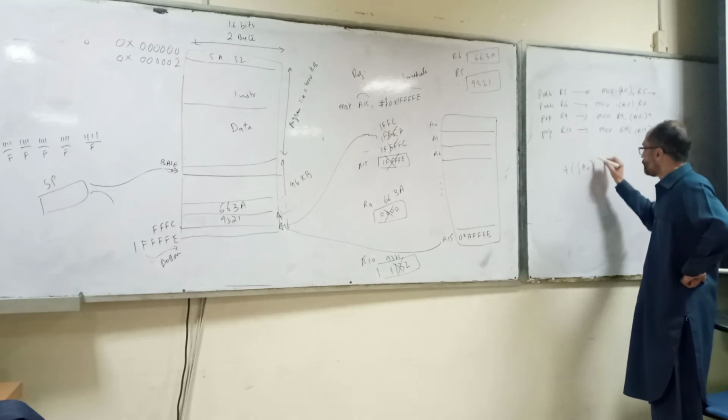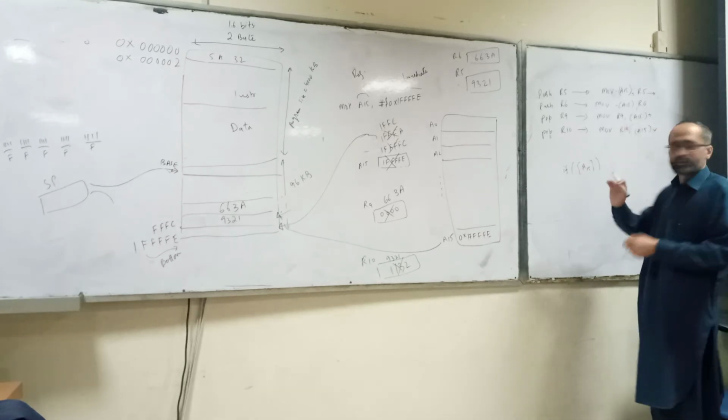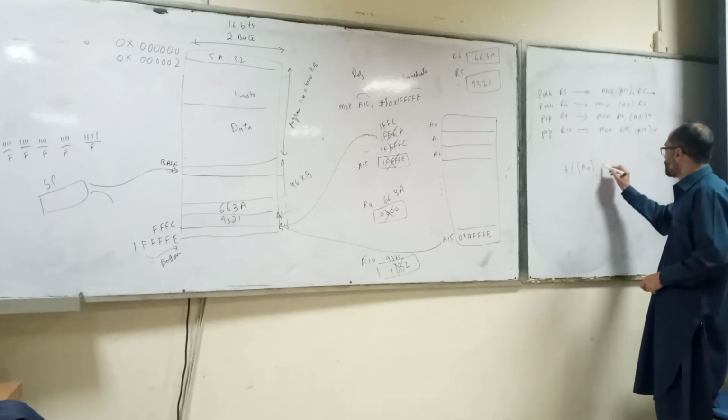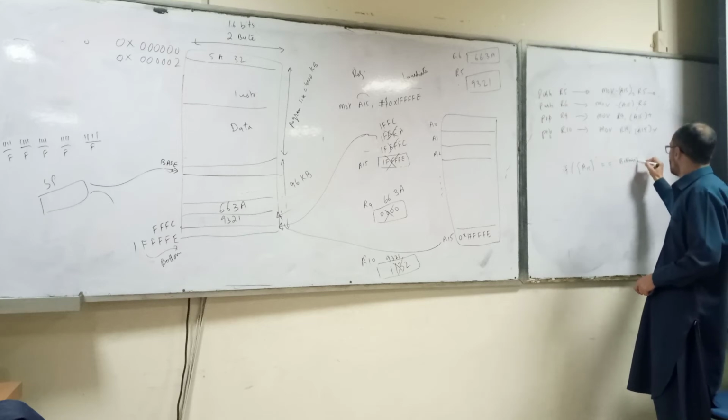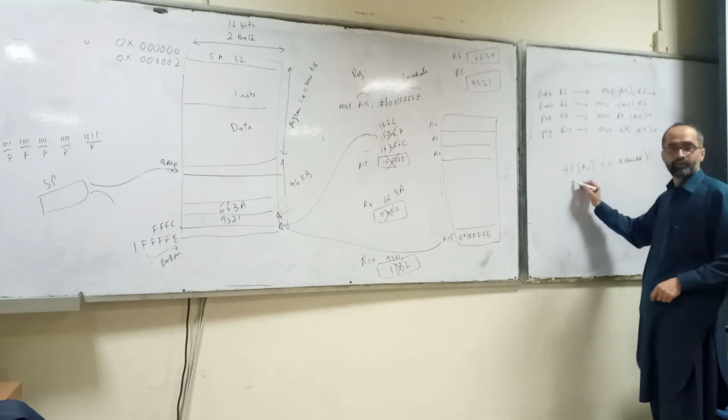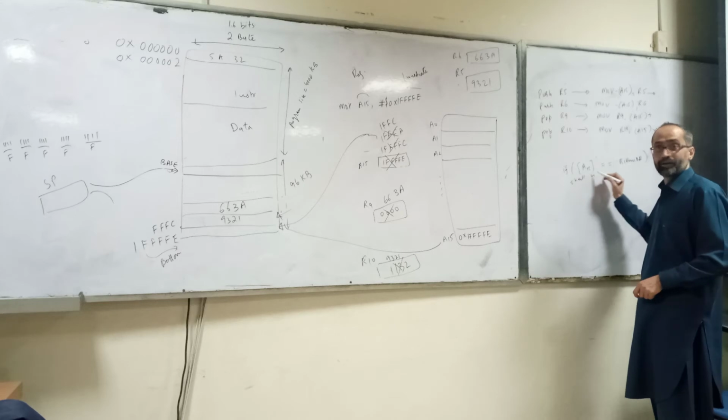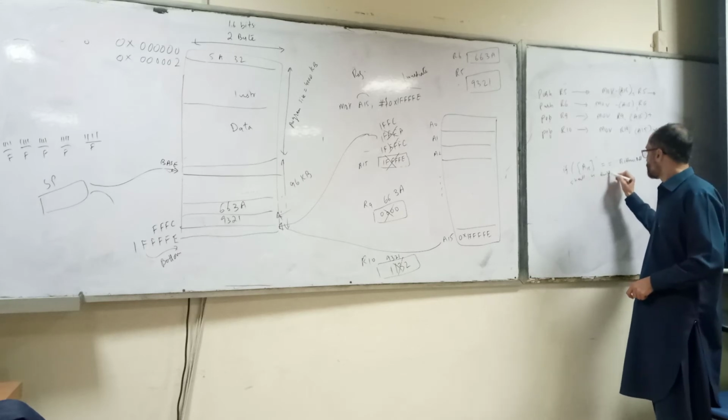If A15, what is A15? A15 is actually the content of the stack pointer. If A15 is equal to bottom address, what does it imply? Stack is empty.